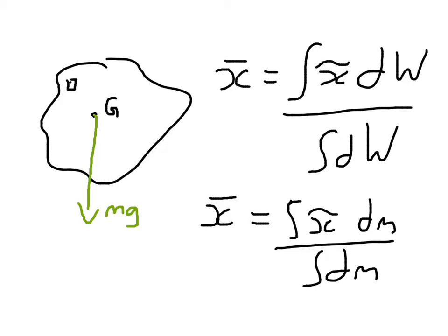If you look at slide 9 of the lecture notes, there are some common centroid positions for some common shapes. So, for instance, a rectangle. The centroid is halfway in the width and halfway in the height. So x bar is going to equal width over 2.